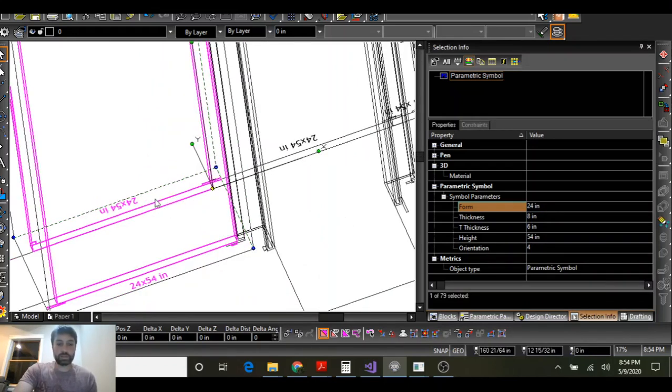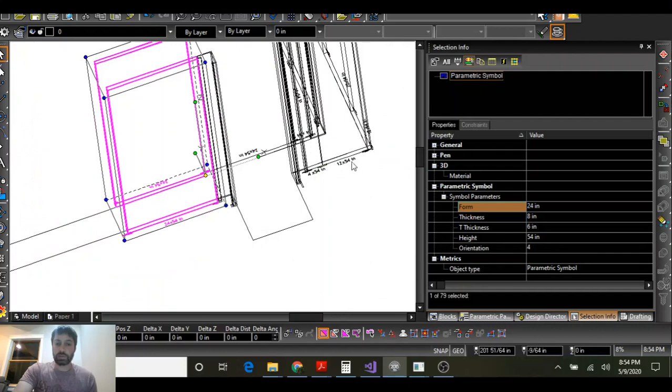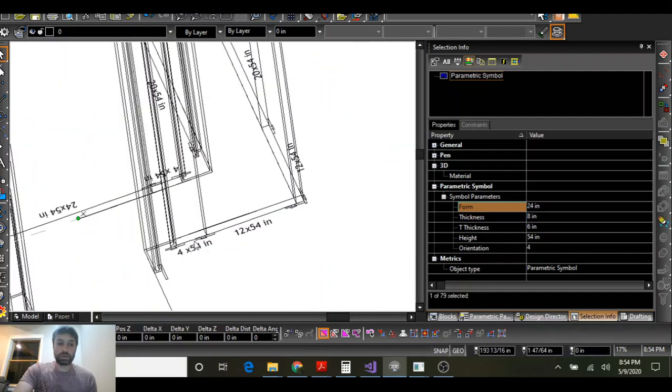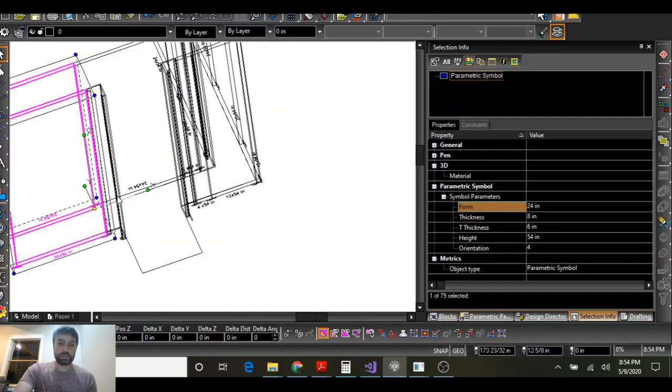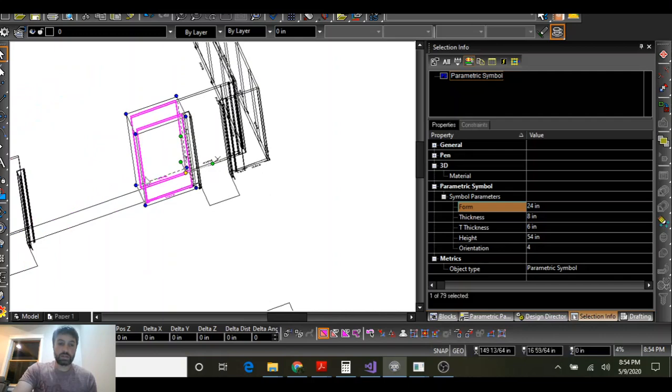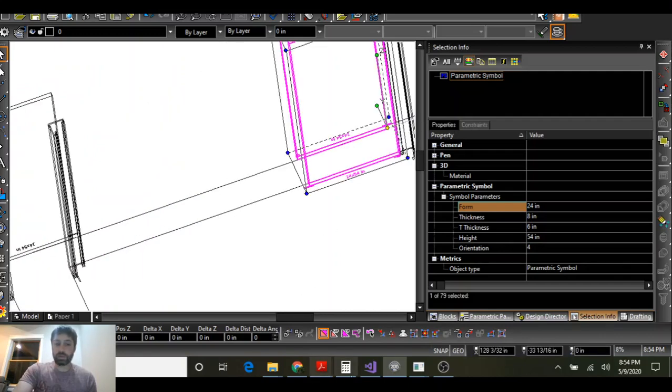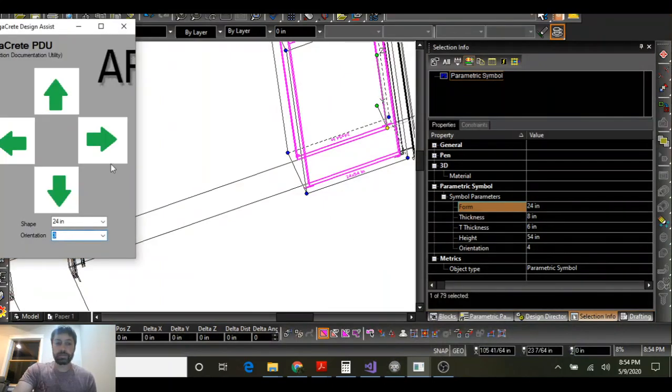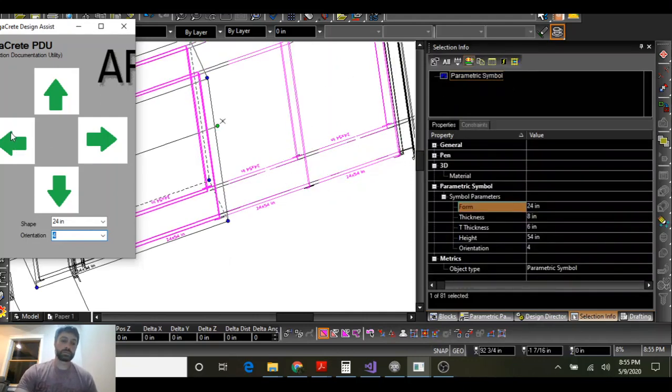I don't have a list that I'm checking off right now of how many panels of different sizes and what this assembly includes as far as an outside corner and inside corner, the different size panels involved with that assembly or this T. Instead, I'm working my way through methodically in a way that I'm minimizing error and maximizing proficiency in the field, letting the computer keep track of the data. That's the goal.